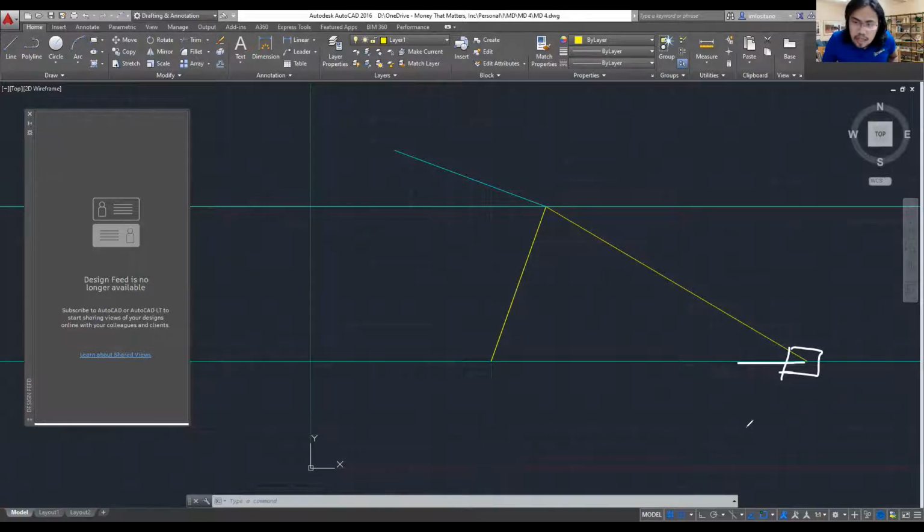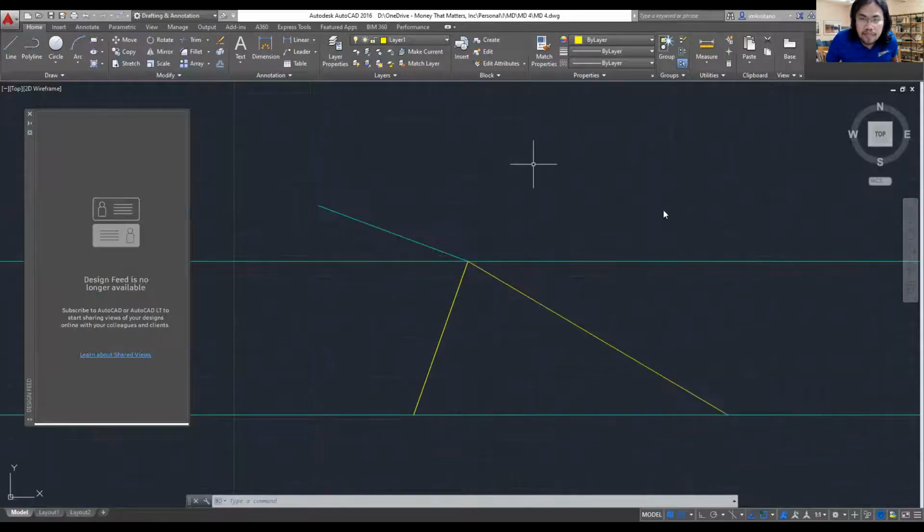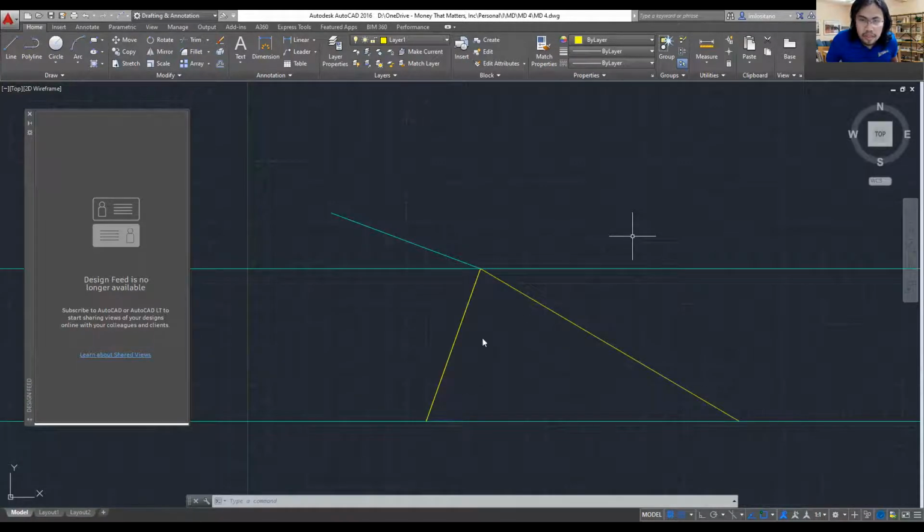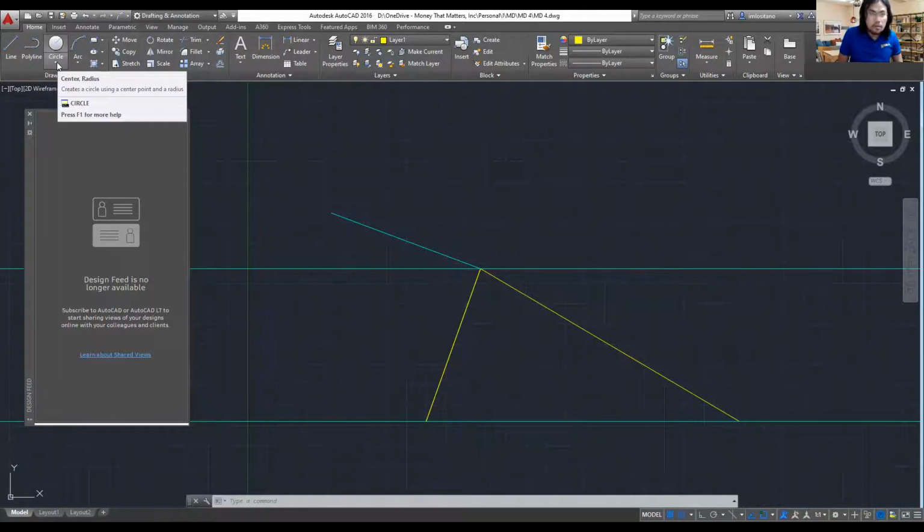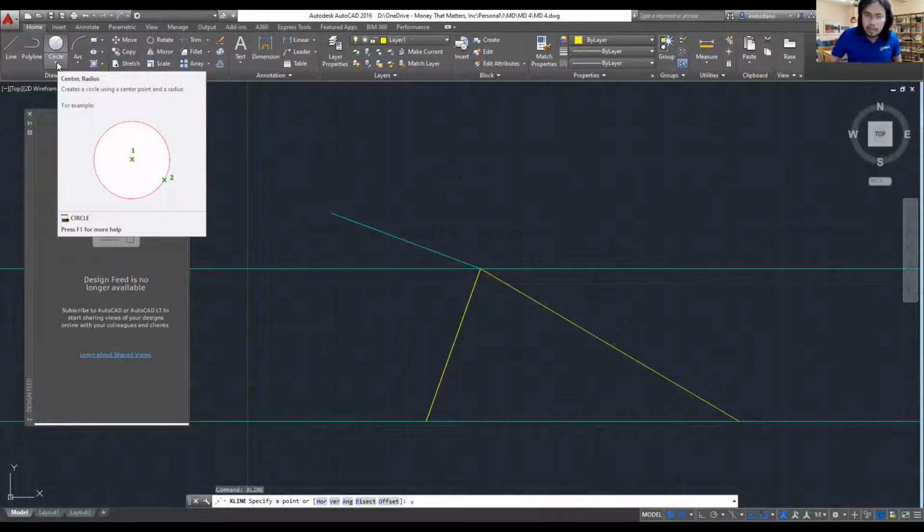We have already this value, right? Now we want to find the instantaneous center of velocity of this link. We know that the velocity VC is along this direction because it's in sliding contact. It's a translational motion. So what we do is we make a line that projects here, this vertical line.